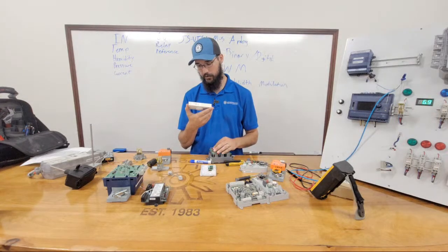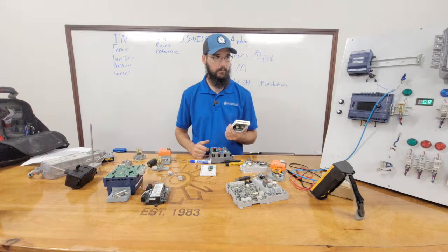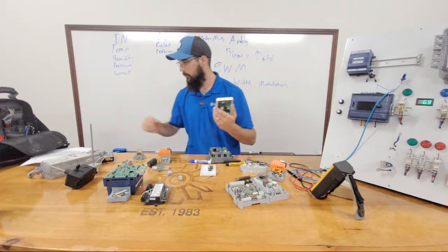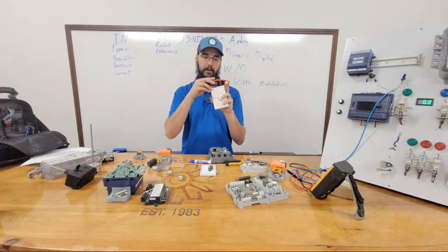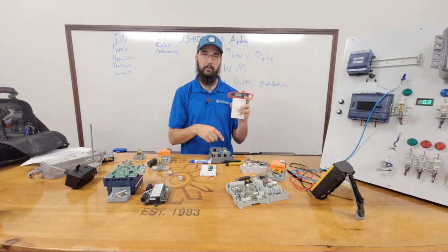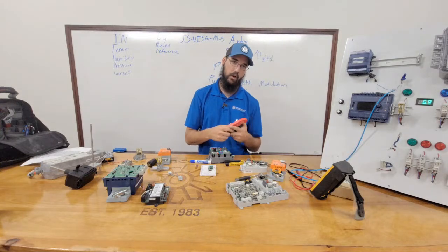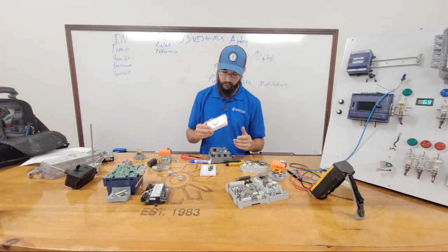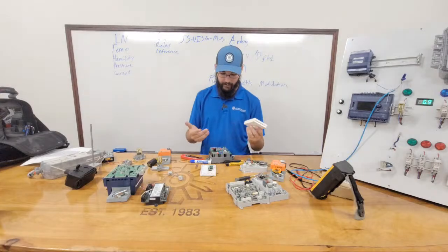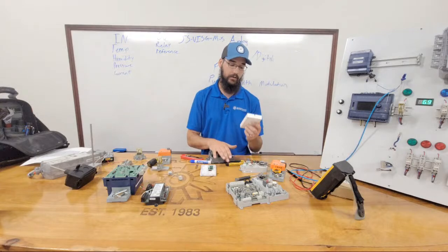Ultimately, when it comes to troubleshooting this, is it reading accurate, first of all? So you put your own temp probe on there, set it up, and is what you're reading right here at the stat actually what the automation is displaying? Okay, so there's one test. If the answer is no, so say you read 70 and this says 75, then you need to verify that it's not the controller or logic causing the issue and it's actually the module here.